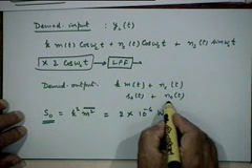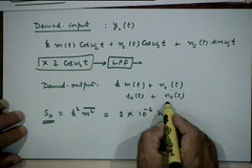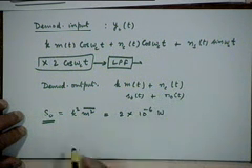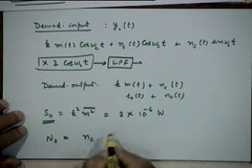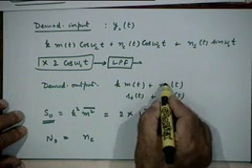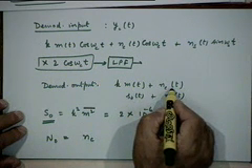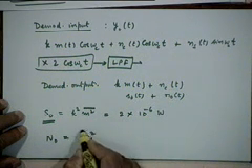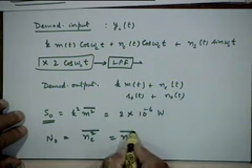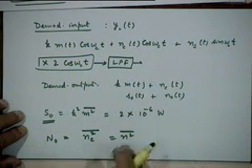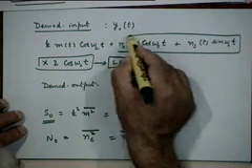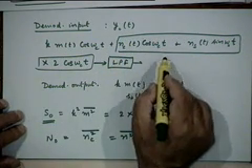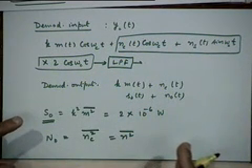The only thing left to do is to calculate the output noise power. So what is the output noise power? It is equal to the power in n_c, this in-phase component of noise, n_c squared bar, which is the same thing as m squared bar. So basically it is the power in this narrowband noise of bandwidth 2B.